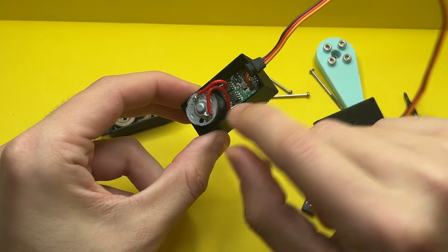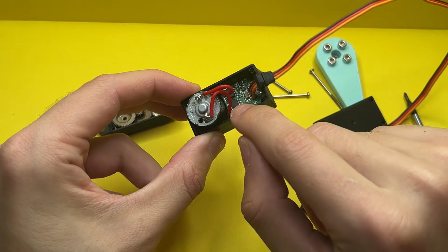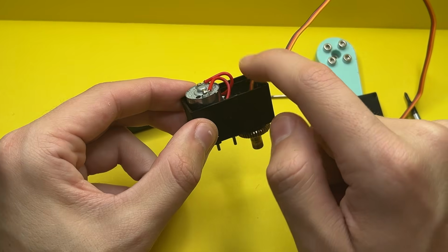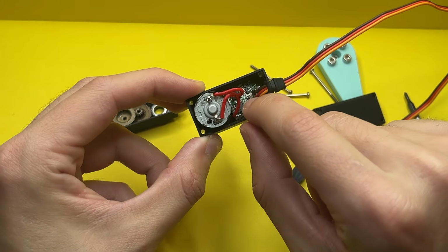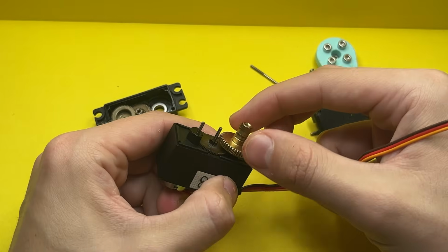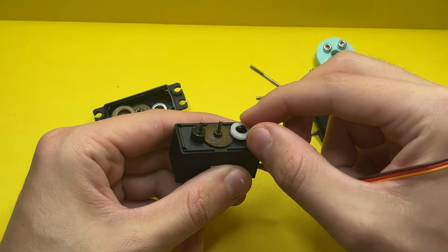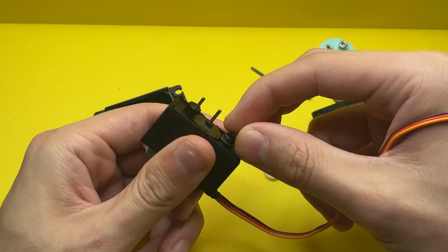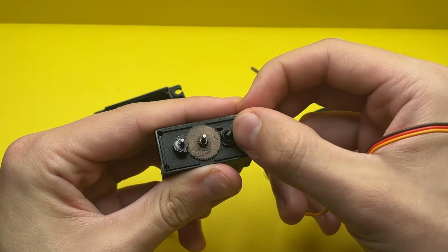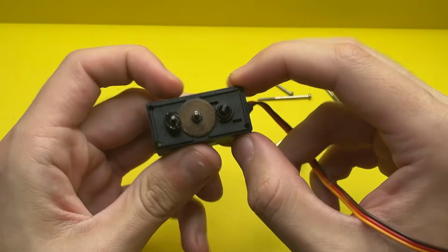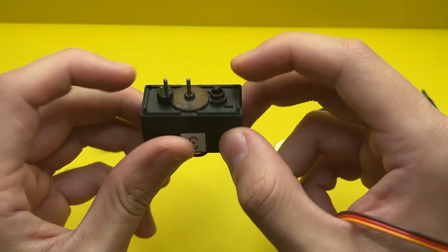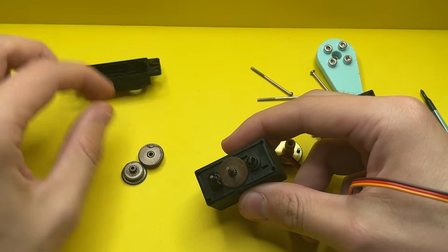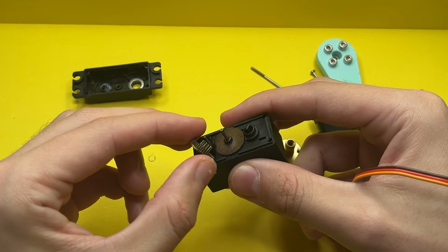Okay, so this thing you see here is the actual motor, while here is the motor driver that I talked about. And as you can see, this is all pretty much just empty space. So this motor driver uses, underneath this gear, a small potentiometer, just like you've seen in our demos. This potentiometer actually measures the angle of the output shaft, and using that it controls this motor. But besides that, we have a bunch of small gears here.